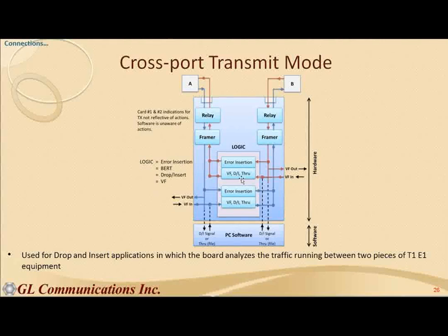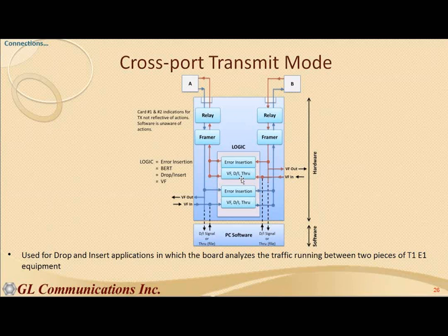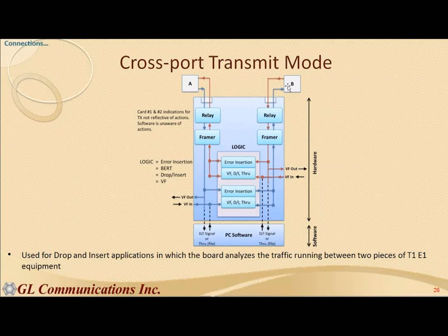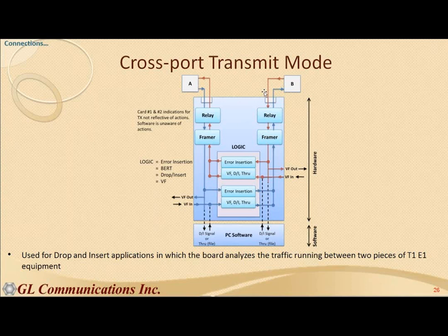Now, drop and insert is kind of a complicated feature. What it means is A can be talking to B in all of the time slots, 1 through 24 or 1 through 30 for E1. But you can alter one of the time slots in either direction and not affect all of the other time slots at all. Sometimes this type of testing comes in very handy, and this also comes in handy for error insertion.